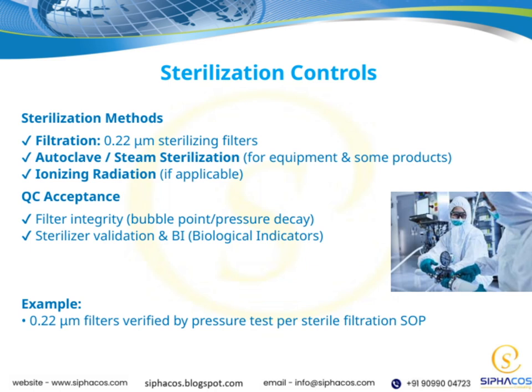Moving on to quality control acceptance, it's essential to verify that these sterilization processes are effective. For filters, we check their integrity through tests like bubble point or pressure decay tests, which confirm that the filters are properly sealed and functioning correctly.